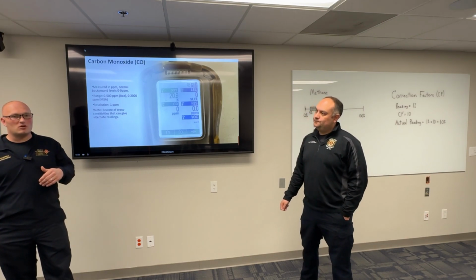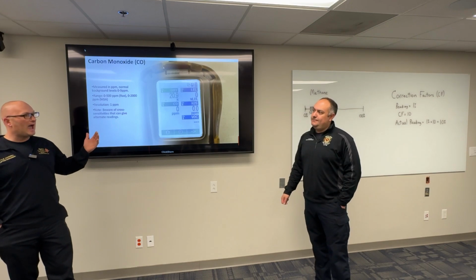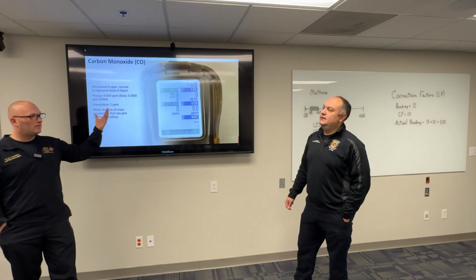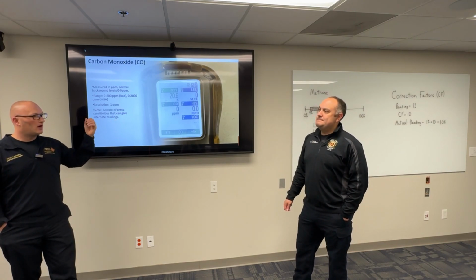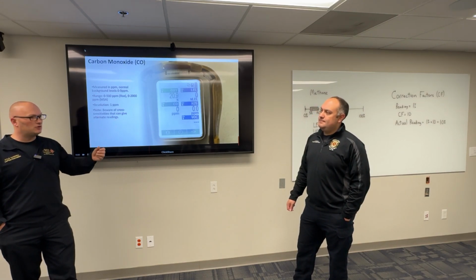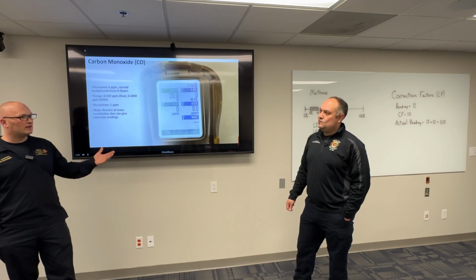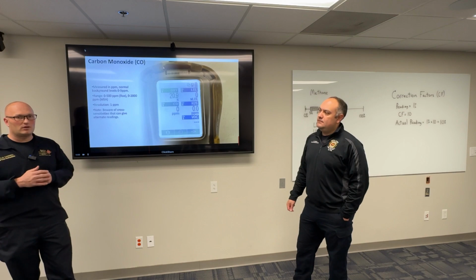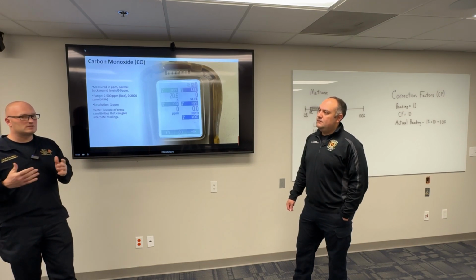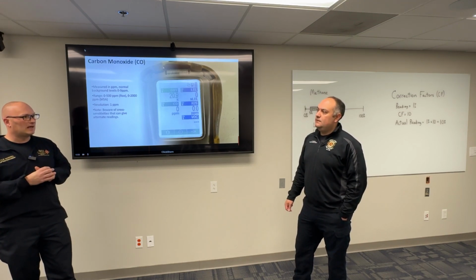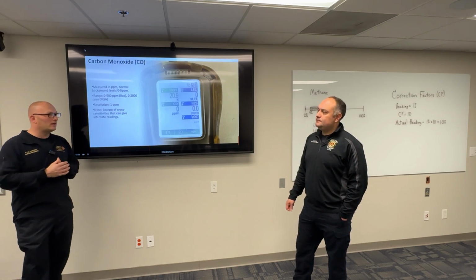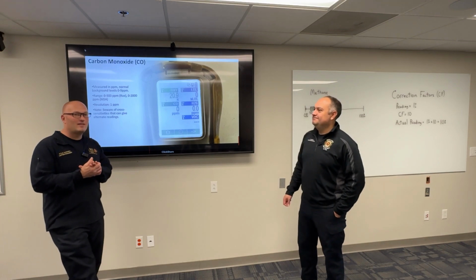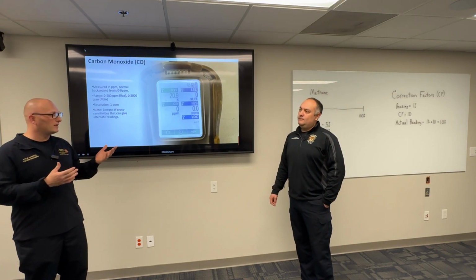So like I've had these calls before where you go in and there's no gas in the house or in an apartment, but because they have cars parked in a garage, by fire code they have to have a CO meter. This thing's alarming, you're getting readings, and you find something that's giving off incomplete combustion or cross sensitivity. So always dive in and look for anything and everything that could be giving off these readings, to really give somebody an answer. I'm not a big fan, I'm sure you aren't either, of leaving calls like, man, I really still have no clue what that was. Dive in and figure out what's going on to give these readings.